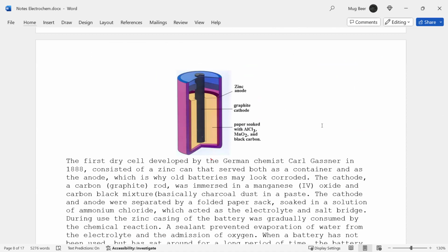And so the zinc produces the electrons. The electrons go to the carbon and change the carbon into something else. This battery has 2 ways to not work. Either the zinc can gets completely used, and that's usually what happens, or the moisture inside of the dry cell evaporates, because this thing can't be completely closed up.